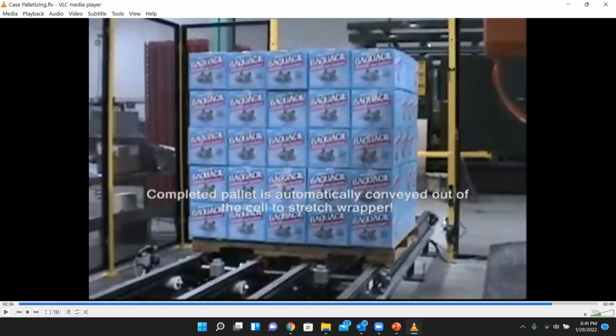Okay, so the plus side is that you have only one manipulator to do the entire job. The negative side is that the manipulator can do only one task at a time. So when it handles the pallet, the arm cannot handle the boxes or the sheet. When it handles the sheet, it cannot handle the pallet or the boxes. Of course, you don't need to handle the pallet when you handle boxes and sheets. So you have to look at that.